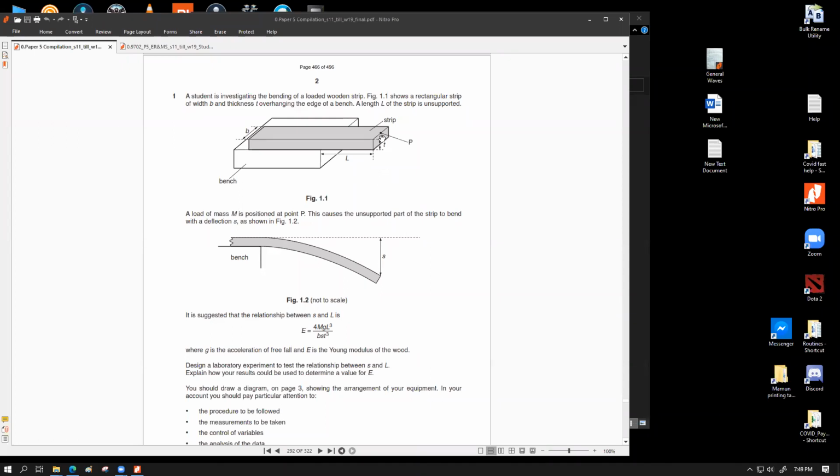You have to place it exactly on this point, as located over here. If we place the load exactly on top of this part, having the loads exactly located on this point P might be a very difficult thing to achieve, because you would have the question of balancing and stability of those loads on the wooden plank. Another very important thing is that measuring the value of S, if you place the loads over here on the top side, might also prove to be pretty difficult, because that way you will be obstructing the measurement point.